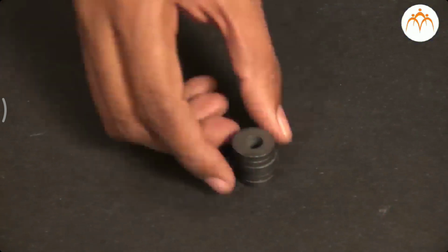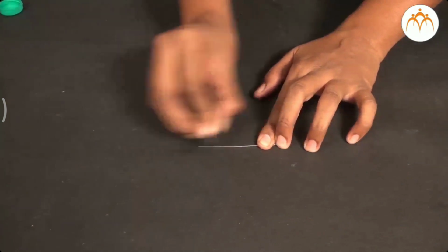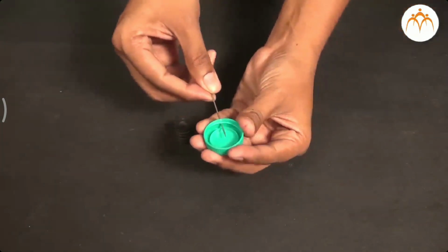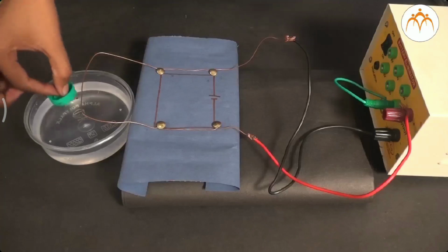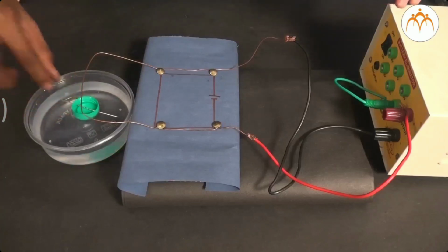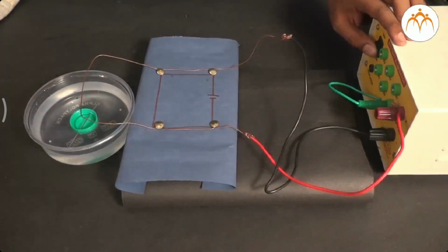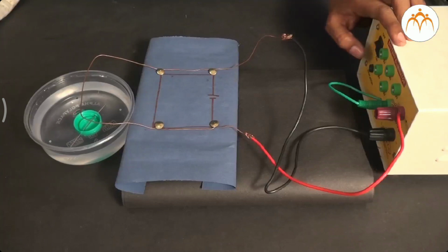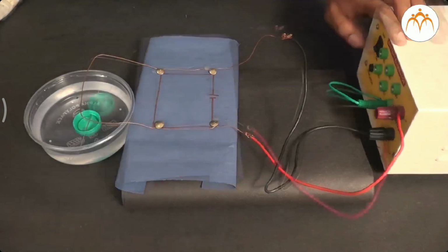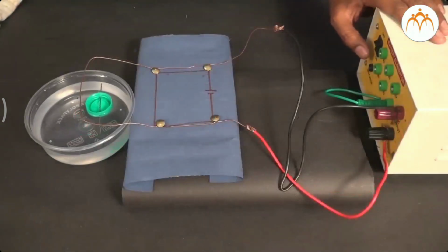Let's perform an activity to know what Oersted found out. Instead of an actual compass, we will use a needle compass made from everyday things. Take a single double A 1.5 volt battery and place it in the circuit as shown. The needle compass is placed next to thick copper wire. When the circuit is complete, current flows through the copper wire, which results in the generation of a magnetic field around it. This field moves the needle of the compass, which itself is a magnet.